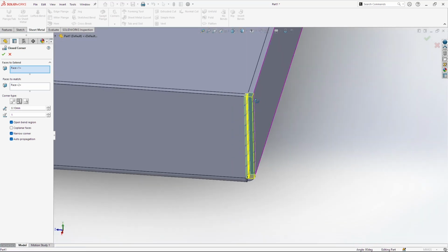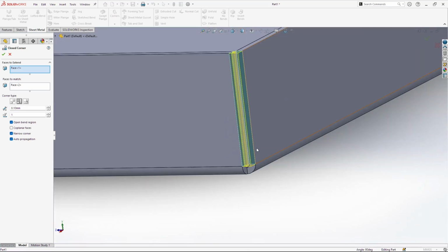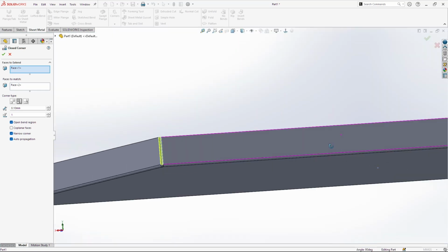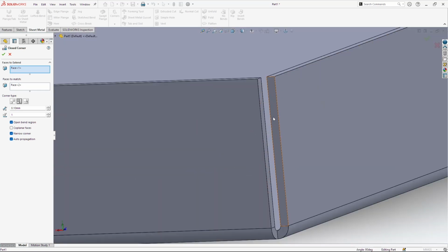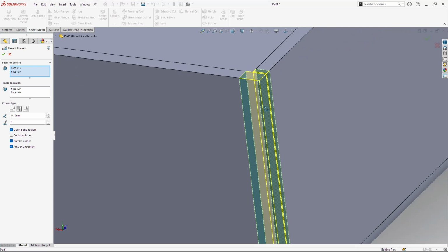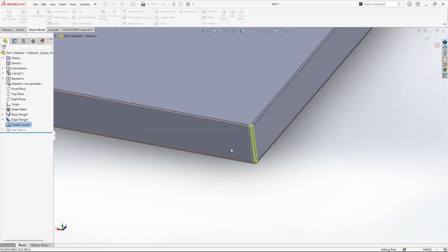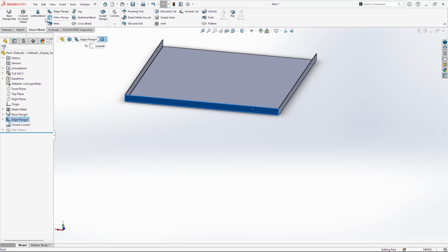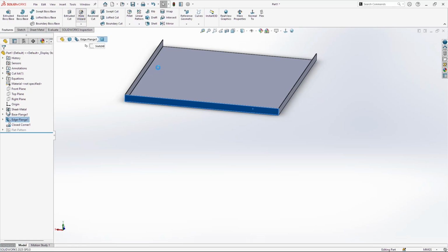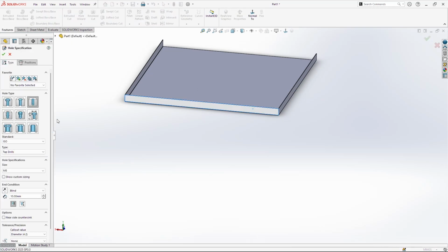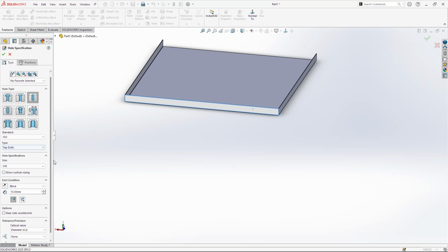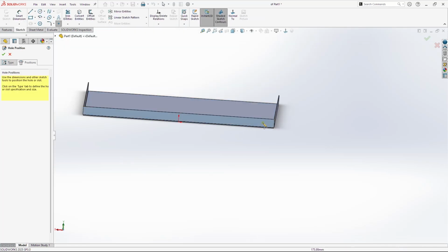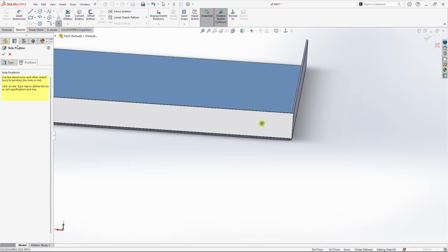We're going to use this option. And of course, select open bend region. Also from this side. Click OK. Then we need to make few holes on this side. We need tap drill, M5, and just make one point here.